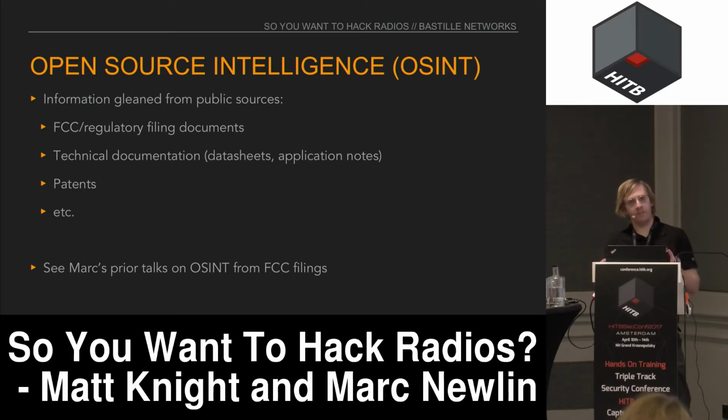If it's not an FCC certified device, you can look for technical documentation. Often it's easier for a manufacturer to use an off-the-shelf transceiver than to roll their own. So you might have transceivers from Nordic or TI or ADI or CC or one of these RFIC vendors. You can either look inside the device or find internal photos somewhere online and look up data sheets for the transceiver that's in the device. That will often tell you all the physical layer characteristics, sometimes packet formats and protocol information and so forth.